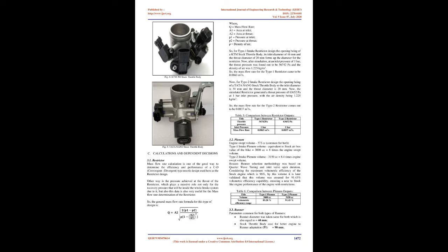There are no well-defined methodologies to define the diameter of the intake throttle body, but by a small calculation and simple simulations we can make a close approximation of how much it should be to suffice and not choke the airflow, as well as big enough to not cause flow velocity losses in air. A CFD test can be carried out of the internal flow path of the throttle body to determine the characteristic and flow velocity that it develops, and to iterate and find out the approximate outlet diameter that should be enough